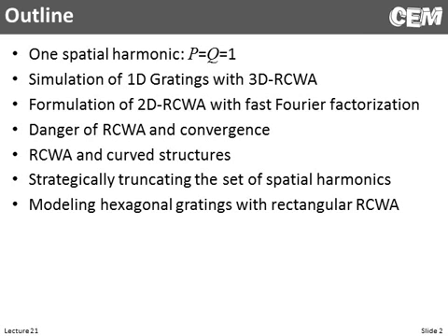And then the last thing, it's also possible to model a hexagonal grating with a rectangular rigorous coupled wave analysis with a couple tricks. We can generalize RCWA, and we alluded to that in some earlier lectures about how that would be done. But rather than reformulate and rewrite a whole code, it turns out we can still do that with a rectangular rigorous coupled wave analysis with a small hit in efficiency.